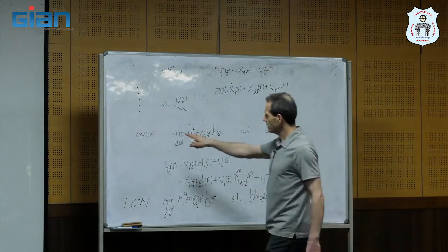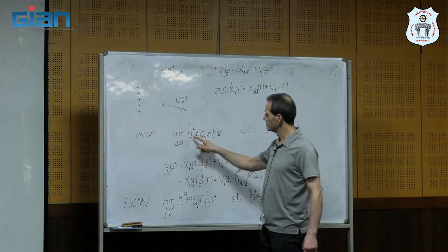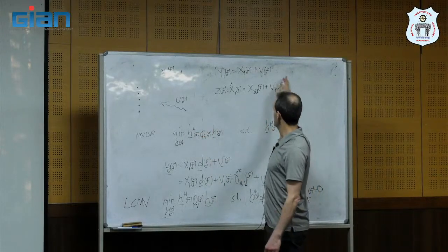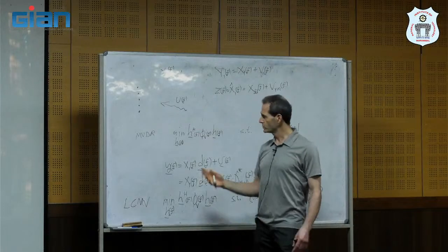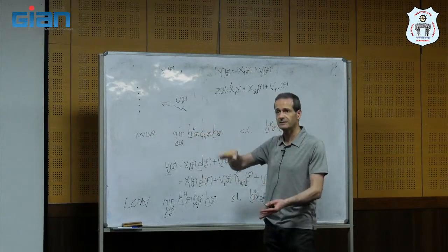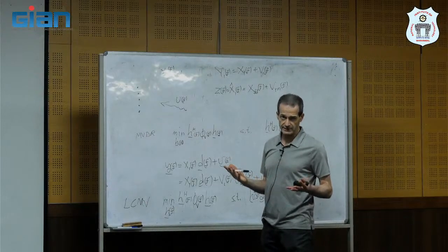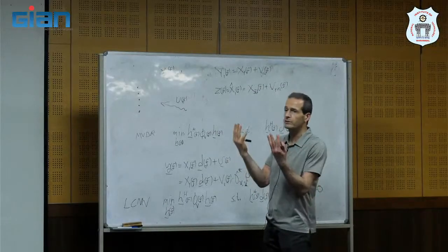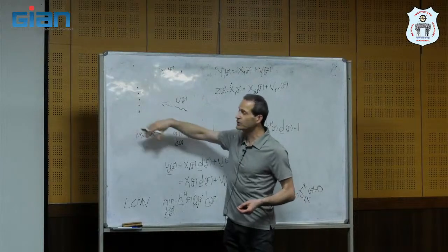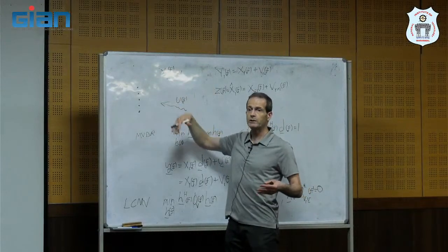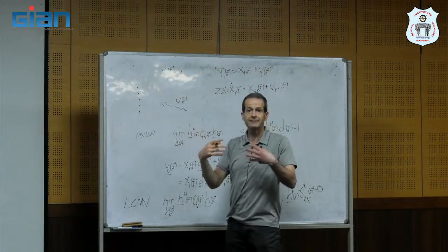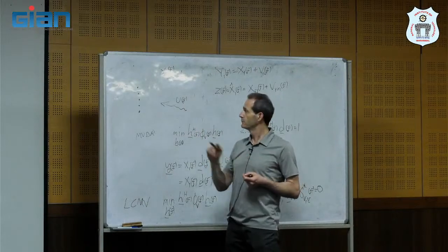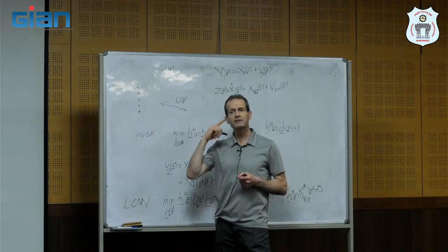So if I use the MVDR, what does it try to do? To minimize the power of the noise, the variance of the residual noise. So it will find a filter that minimizes this variance, the power of the residual noise. So it will try to minimize the amount of energy. If we have stationary noise, it will put more effort to minimize the more powerful noise, which is the stationary. Because this has very low energy, but it's very disturbing.